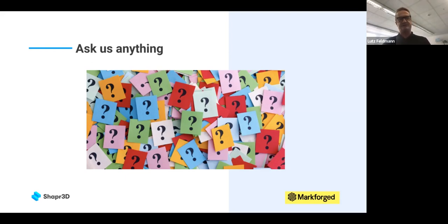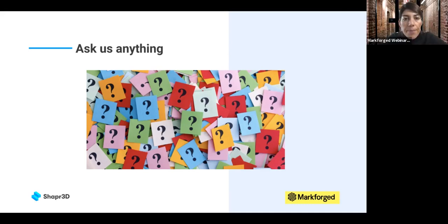Actually, I have to say, if you look at our technology and you think about generative design, there are some limitations for us because our fibers are laying down in an XY area. So if you want to use generative design software, you need to make sure it has the boundary conditions of just being available in XY. So that's one of those points.